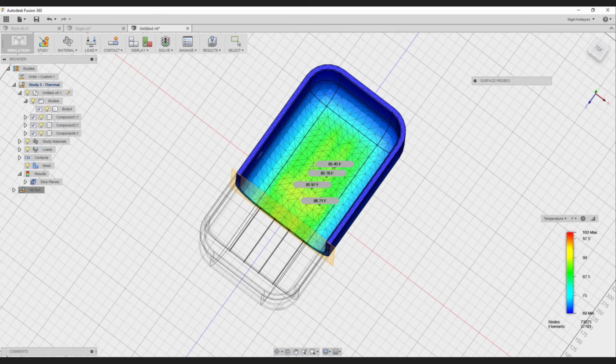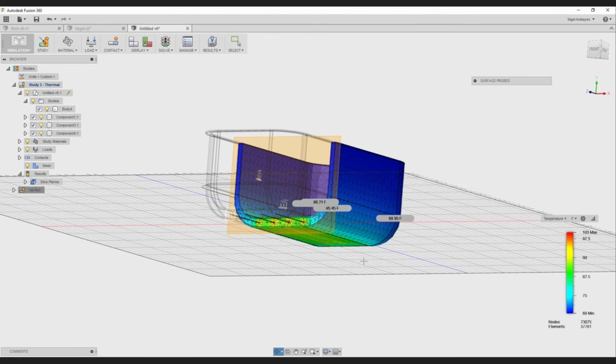And why is there a difference here? So the difference I made here is, if you look at the model, go to the home view here real quick, or I'll just rotate this guy. If you look here at the model, okay, if you go here and look at the heating element and the surrounding area, in the original model we created that as polycarbonate.